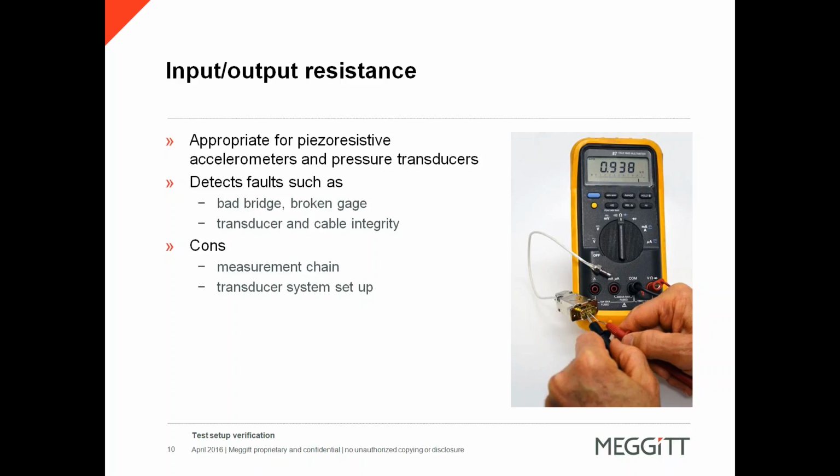considered for replacement. This true health check will tell you if there is an open or cracked bridge, as well as any significant changes or drift from the transducer's original resistance. This is thus a very easy method to check the integrity of the transducer.